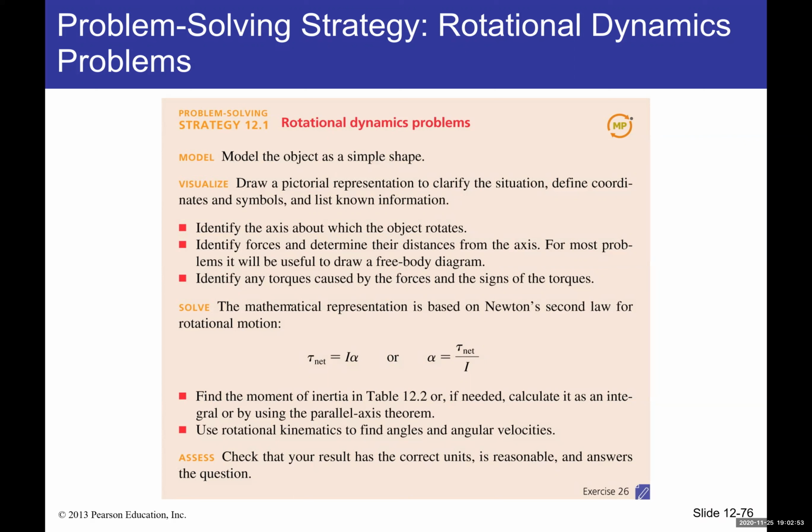But always have the coordinate system and the free body diagram, which also allows you to look at the torque and the orientation of the torque, clockwise, counterclockwise, and things like that. Then you can combine them all together in this equation along with the kinematic equations.